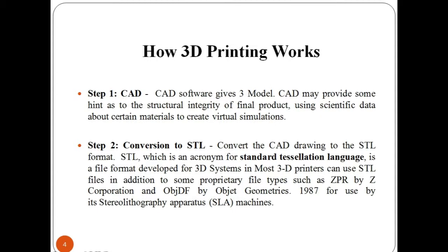Select an orientation or position in which the part will be built and then let the software do the rest. It sections the design into layers and creates a tool path for both the part and its deposable support structure. Now click print to send the build file to the 3D printer.